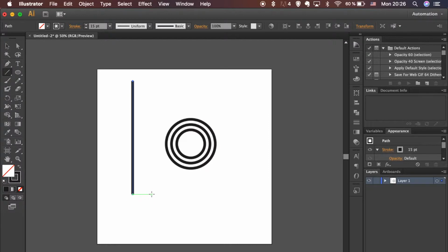Select Line tool. For the line to be straight, drag by holding Shift key. Press Shift key as you rotate if you want to snap the rotation to 45 degrees. Drag line onto the circles. Copy the line, it will be necessary a bit later.